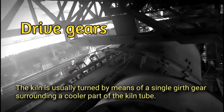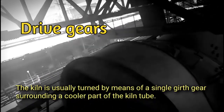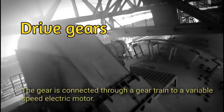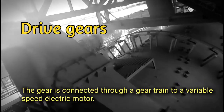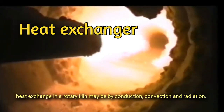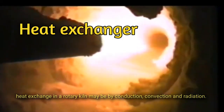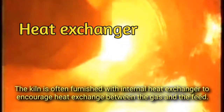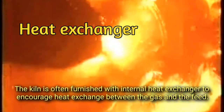Drive gears. The kiln is usually turned by means of a single girth gear surrounding a cooler part of the kiln tube. The gear is connected through a gear train to a variable speed electric motor. Heat exchanger. Heat exchange in a rotary kiln may be by conduction, convection and radiation. The kiln is often furnished with internal heat exchangers to encourage heat exchange between the gas and the feed.